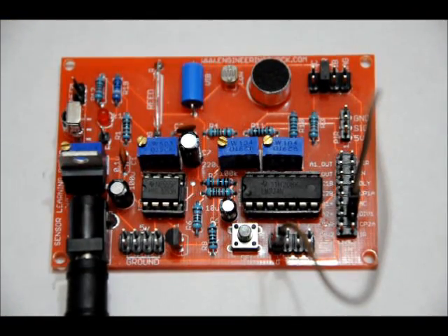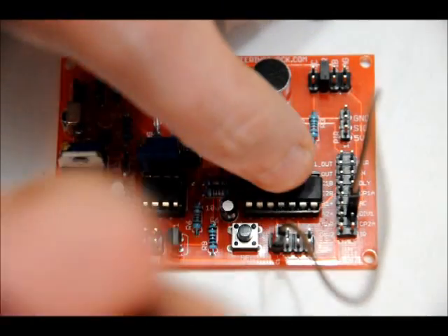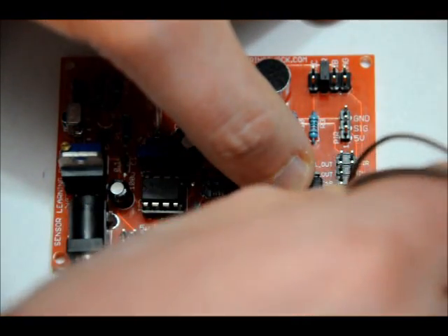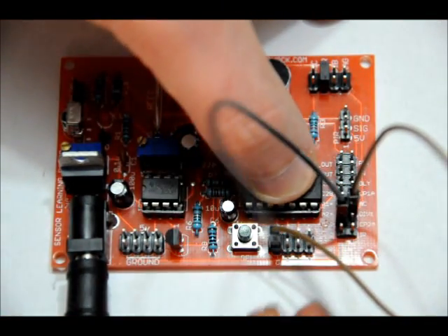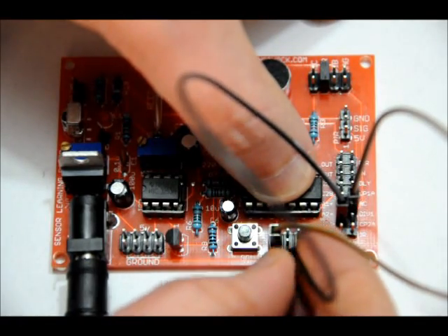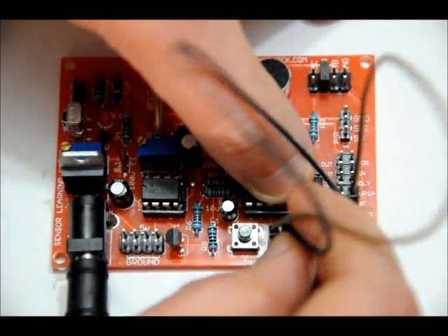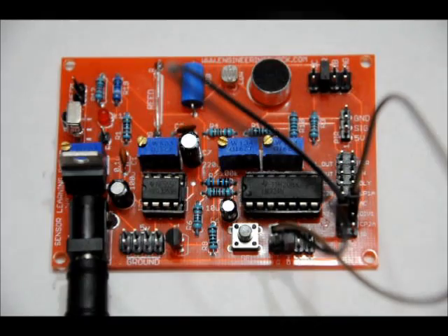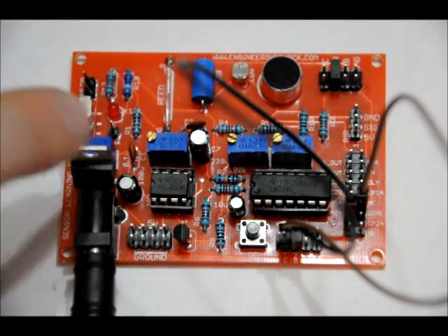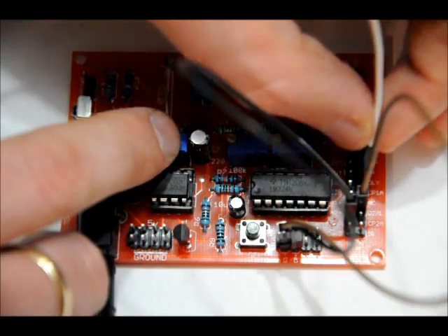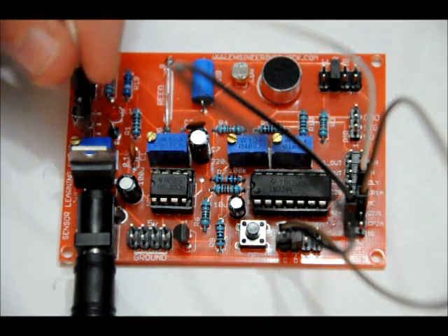Now we'll connect our VAR pin that we've set to 3 volts to the C1+ pin. Sorry if my hand's getting in the way. Lastly, we're going to take our CP1A, our comparator output, on the main pin block, and connect to our LED pin.